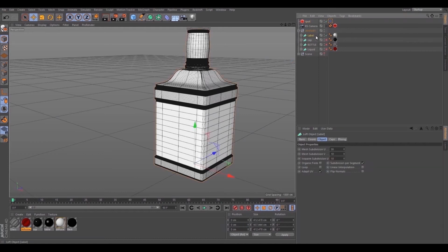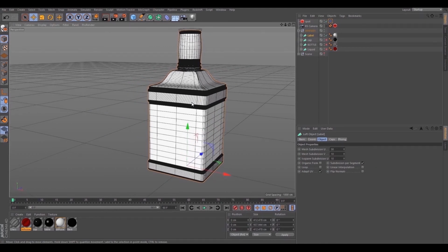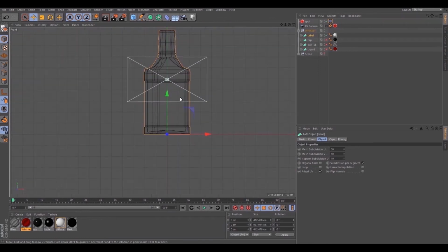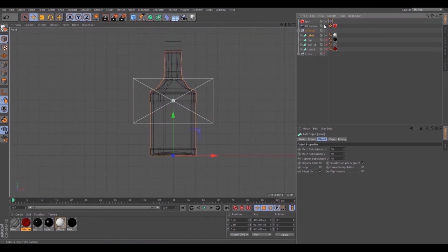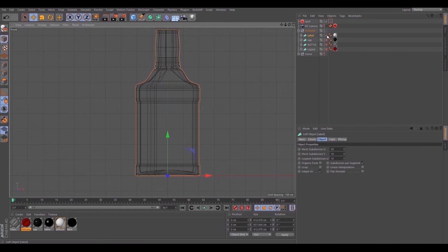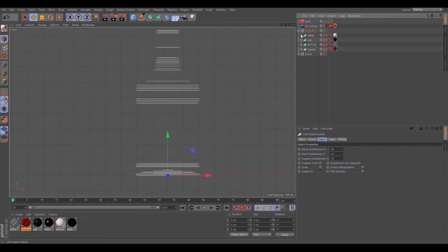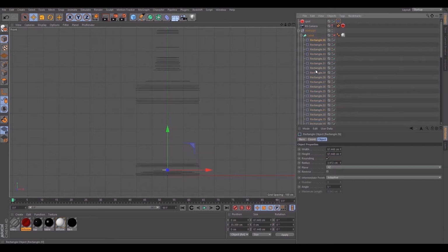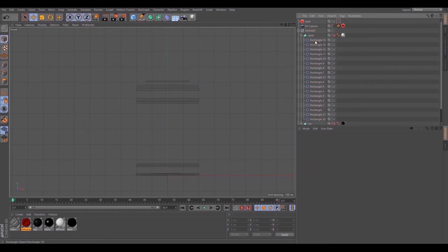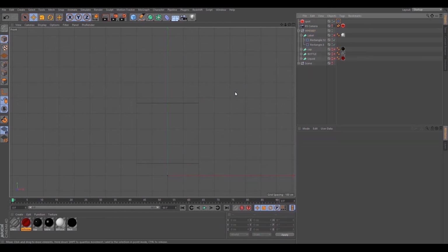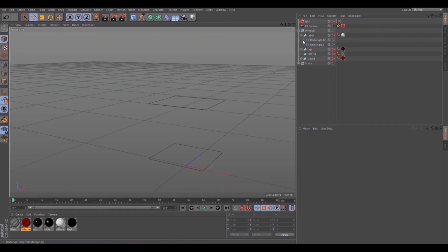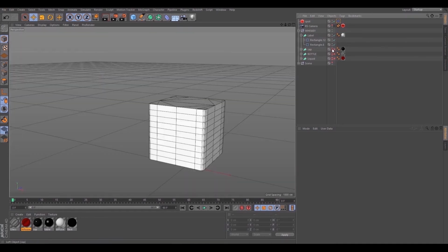We need to delete all useless shapes from loft. Go in front view and switch off the visibility of camera in viewport. And then delete all circles and rectangles except these two in center. Let's see what we got.